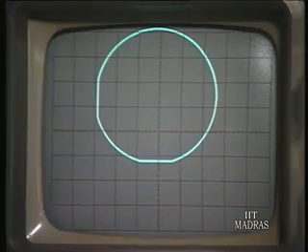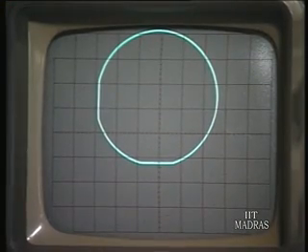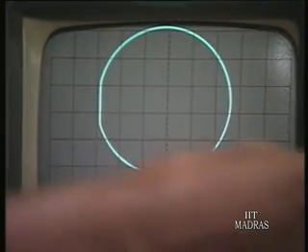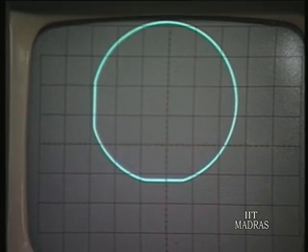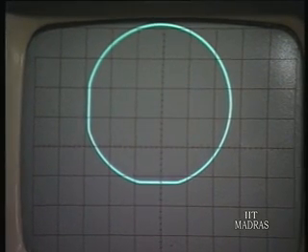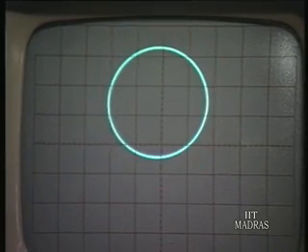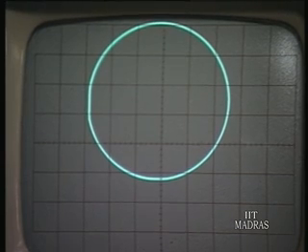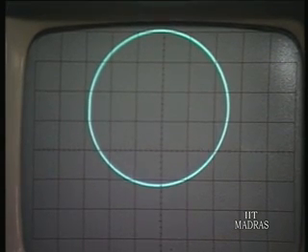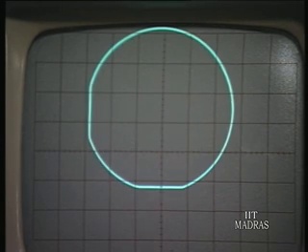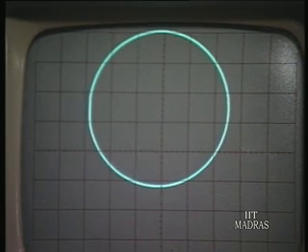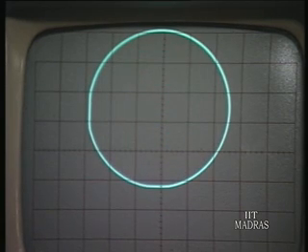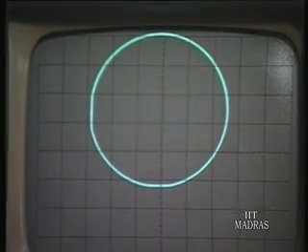So, this is a perfect circle, you can see, because the amplitudes are the same and there is a phase shift of 90°, and it is a perfect circle. X squared plus y squared. See, she is changing the feedback. So, the amplitude changes slightly, but it is vanishing, and when it is growing, both are growing simultaneously. That is perfect quadrature output. This is the beauty of the quadrature oscillator. Thank you.